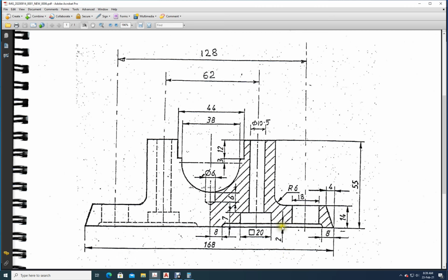From this point I will go 84 up to this. Then I will start tracking, use tracking, and then base point is this. Then again go up and come like this to draw this line. Then I will draw a line like this. This part I will do first, right? Fine, that would help me to finish this portion easily.